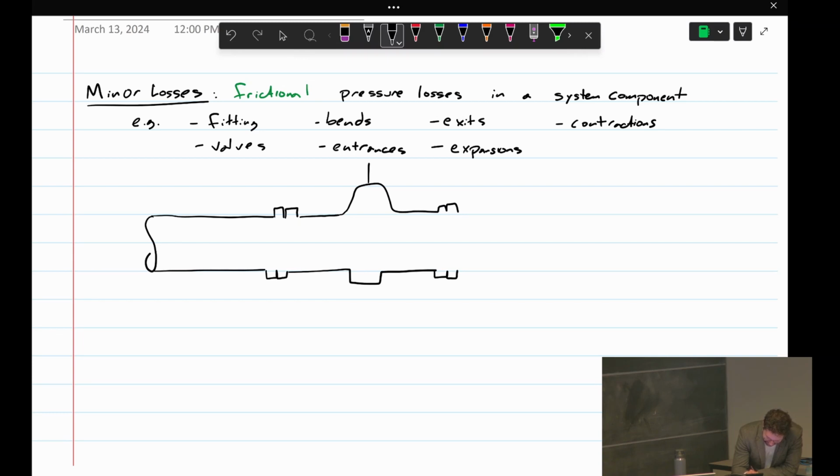So this is my best impersonation here of a gate valve. So inside a gate valve, there's this big gate, just like in the name. And when you raise and lower that handle, it raises and lowers this gate to close off the flow. So this pipe continues here.